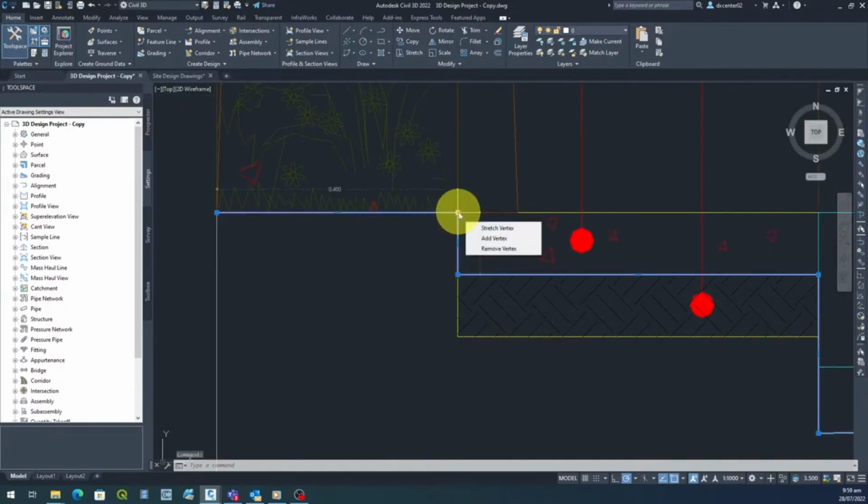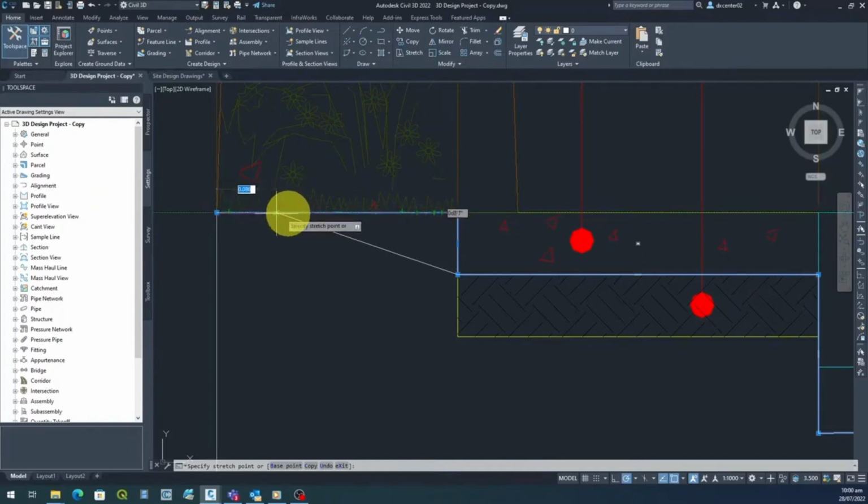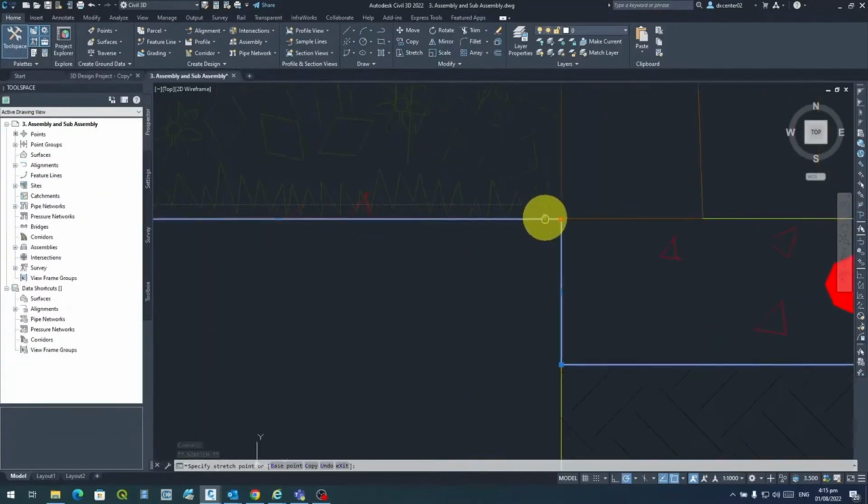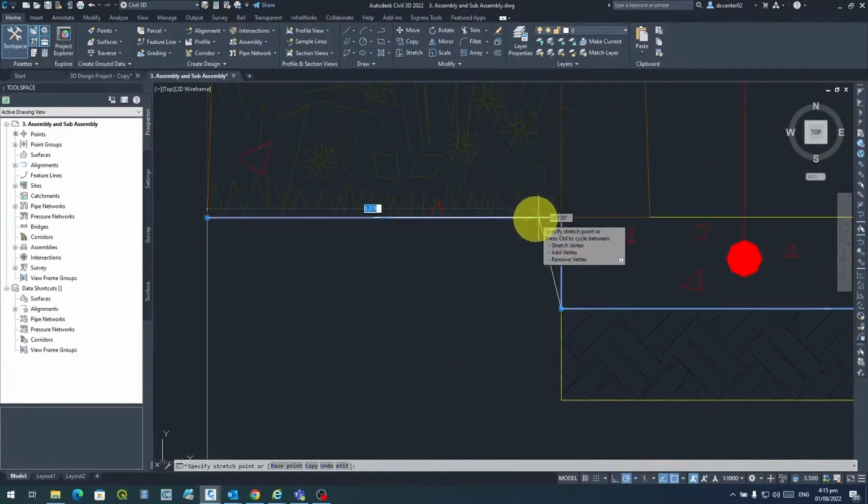To make this a slope line, select the polyline. Then, left-click on the vertex you need to move. Right now the editable length is the horizontal line from the left side to the first 90-degree turn. But what we want to edit is the distance from the original vertex position to a new vertex position.